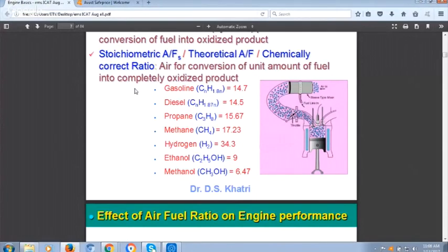So this is interesting. You can think, can I make a logic in the filter? I can put in my vehicle that when it gives the light, I should change the air filter. Then we say, now you don't change the air filter when the light comes. You clean the air filter and reuse it. Then you can do it 3 times. After that, its dust holding capacity will be totally that of the paper.